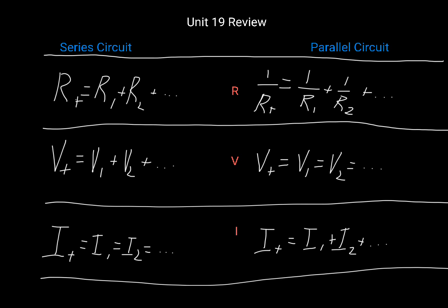You all may recognize that what we do with voltages in series is how we deal with currents in parallel, and vice versa. How we deal with currents in series is how we deal with voltages in parallel. This can be helpful if you remember it this way. That way you only have to remember what we do in series and then flip it for parallel, or something like that. As long as you keep straight how we deal with voltages and currents in parallel and in series.